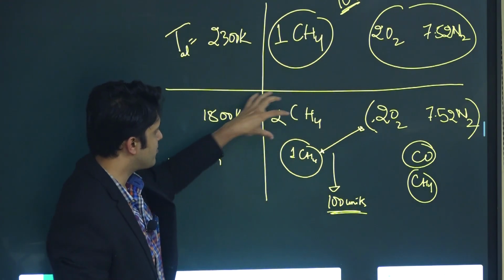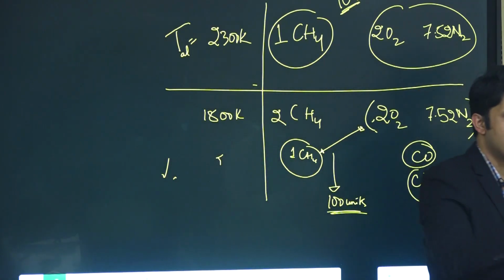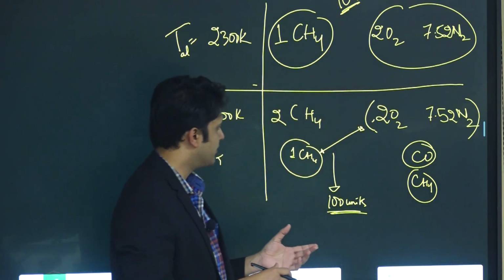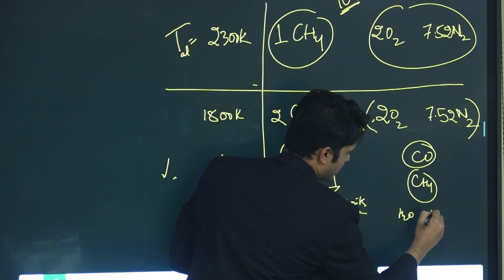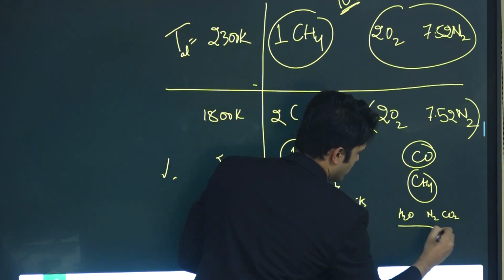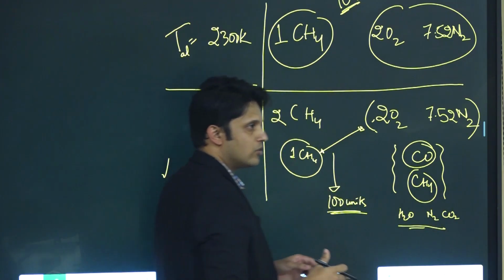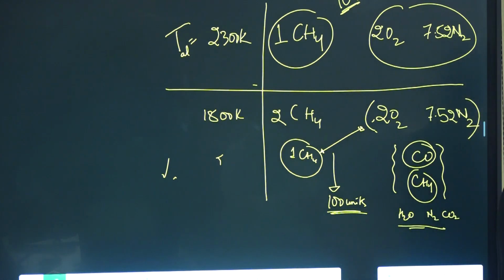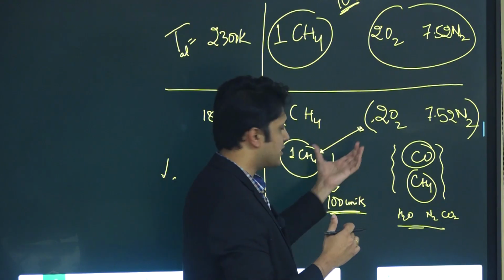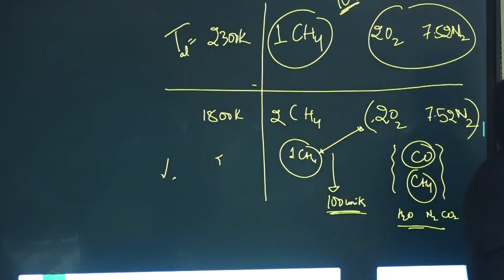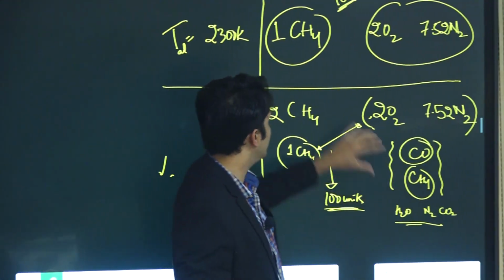And now in the products you have some additional methane hanging around, right? That is additional mass on the product side. So along with water vapor, nitrogen, and CO2, you have these additional components that will also absorb the heat. So in m Cp delta T, you have some added mass, Cp is there, so delta T has to go down to maintain the same energy. The temperature will go down because you have some additional unburnt or unreacted species in the product side.